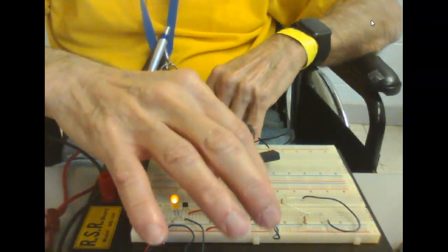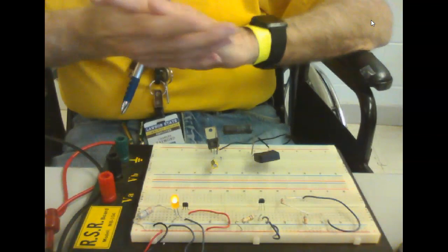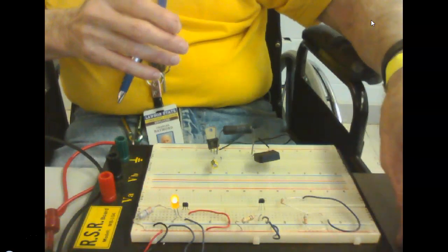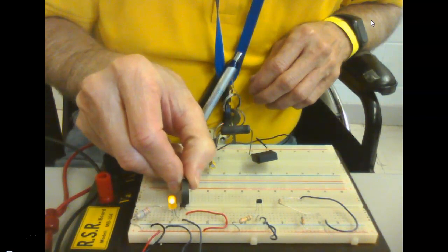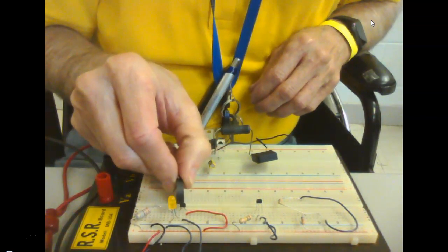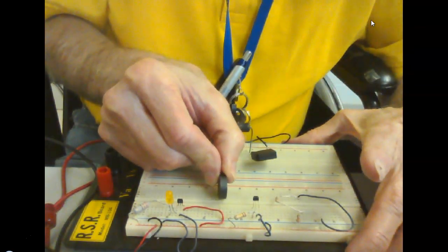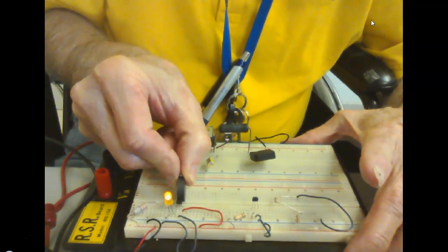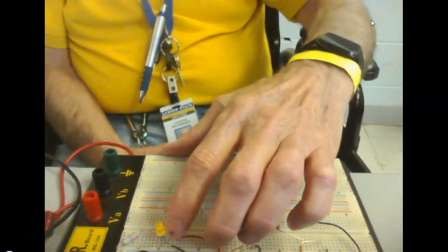This is a linear, but like I said, I'm going to have to go back and see if it's wired up right, because it's not working. A linear will give you a voltage out that's proportional to a magnetic field. A latching, which is what I'm showing, once it sees the field, it'll latch. This one's really sensitive. If this was on the back of that cylinder, it would say, okay, I'm at this position, and when the magnet went away, it would say I was at the other position. So this is a latching Hall effect.